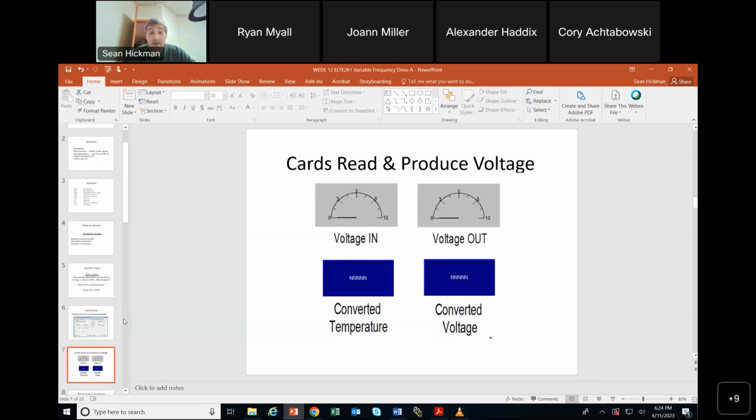So here, all right, ready? I'm going to ask you, if I turn my voltage up right here, my input to 5 volts, everybody, what temperature pops up here? 212. That's right, 212, because it's set my input card to do 212. So then if I set my output card and said, hey, 212 degrees means 5 volts, it would take the 212 and push this right here to 5 volts.